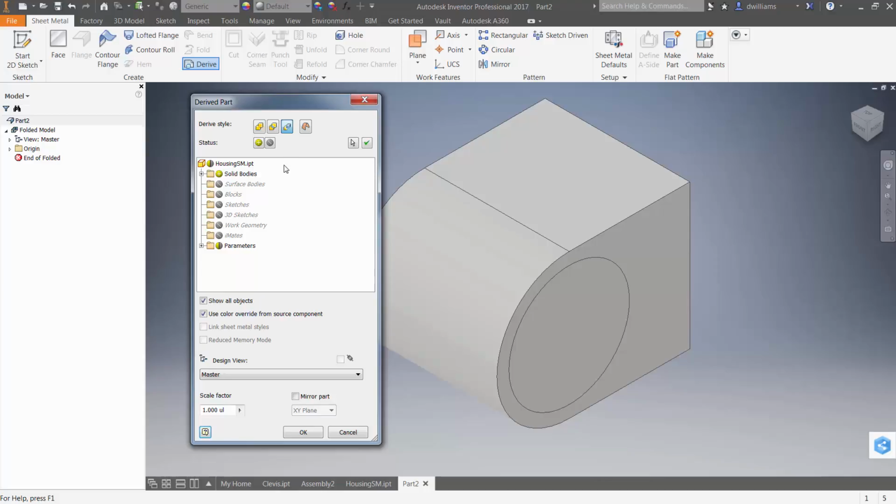And what I'll do here is I'll go ahead and create something called a work surface. Now a work surface is particularly useful for creating assemblies that are made up of sheet metal parts and/or plate, and you'll see why shortly. Notice that I can also import a number of other aspects of that skeletal model.